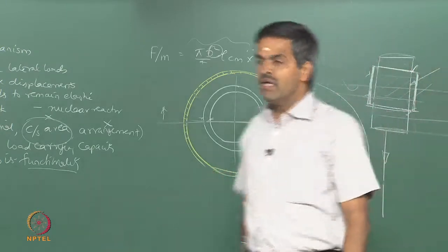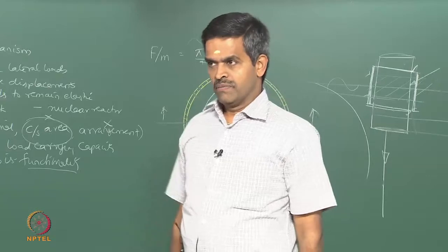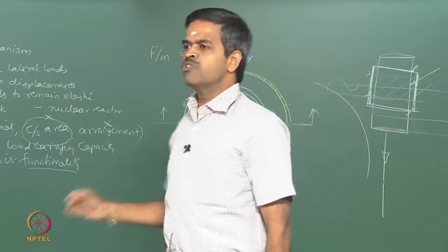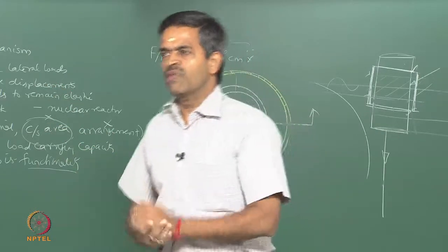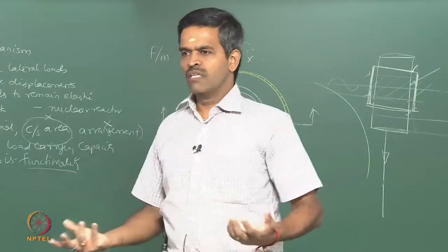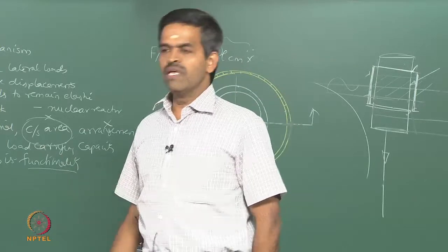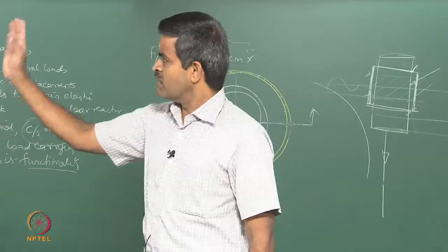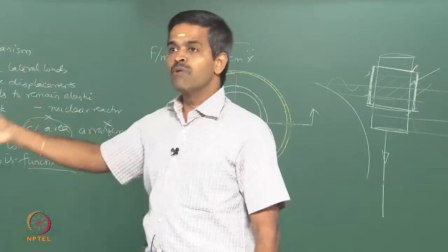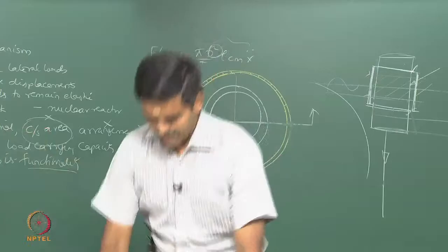So, without doing any numerical analysis, it is directly available. Once you know the velocity, you substitute in the Morrison equation, get acceleration, get the forces and design the system. So, it is very easy. This has been converted into a design chart, which is a direct visible output for the researcher as a design engineer.